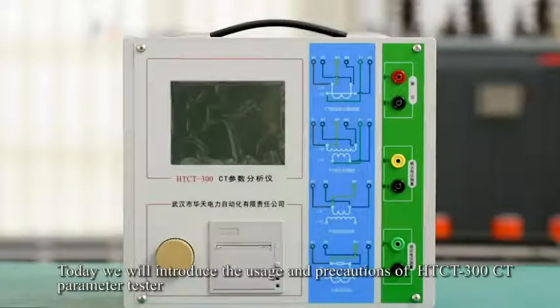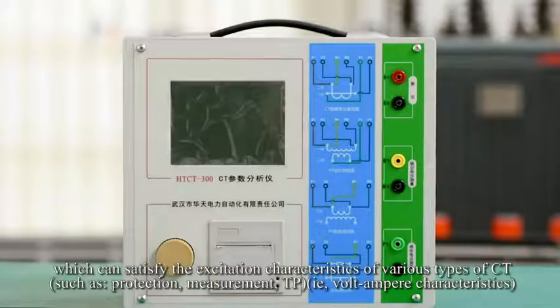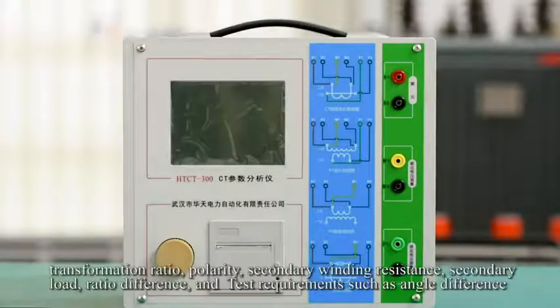Today we will introduce the usage and precautions of the HTCT-300 CT parameter tester. This instrument has comprehensive functions. We can satisfy the excitation characteristics of various types of CT, such as protection, measurement, TP, volt-ampere characteristics, transformation ratio, polarity, secondary winding resistance, secondary load, ratio difference, and test requirements such as angle difference.